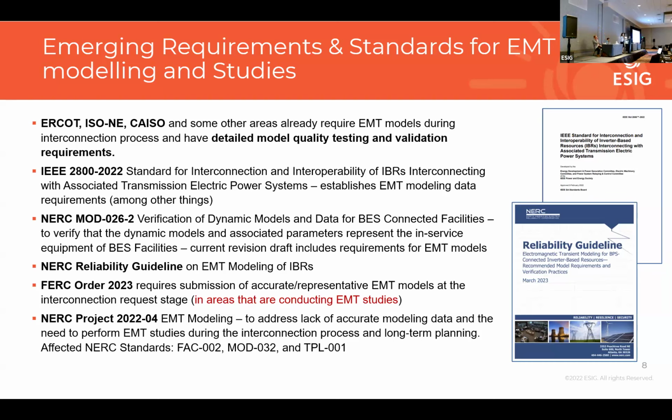these are inverter-based resources connected at the bulk power system level. They have released a reliability guideline on EMT modeling of IBRs. The FERC order from fourth quarter 2023 also requires submission of accurate and representative EMT models at the interconnection request stage.